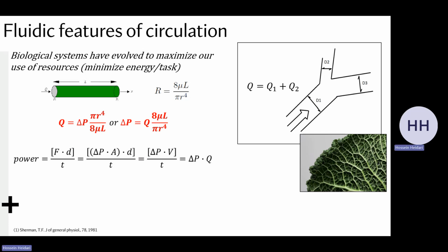So that's the delta P times the cross-sectional area, times the distance over time. Now, if you multiply surface area and distance, the length, it will give you the volume of that chunk of liquid that you're trying to displace, times the delta P over time. And you've seen this if you've looked at piston cylinder equations, the delta P times volume is the equation you use to figure out how much energy. And then if you divide the volume over time, it's going to be the volumetric flow rate, Q.